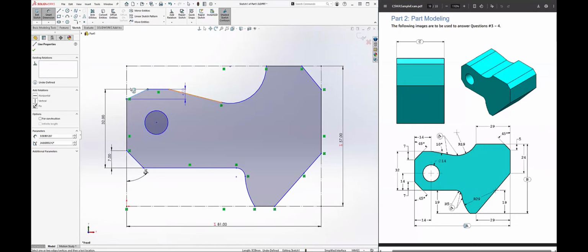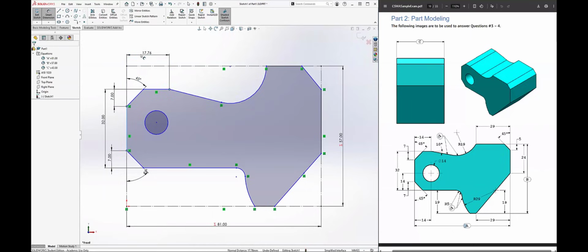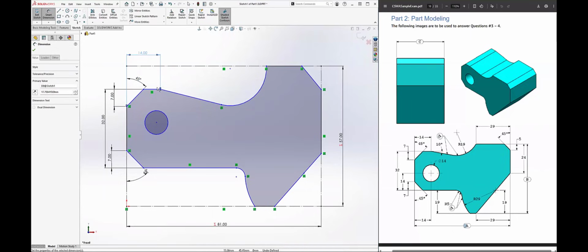Sometimes it's very shallow. You might not snap to the appropriate one. So please make sure of that. Let's add 7 here. And once again, we'll do 45 here. And then we're going to add another one, which is 14 to outside here. Angle here of 10. And also with angles, it'll snap between 3 different angles between the 2 lines.